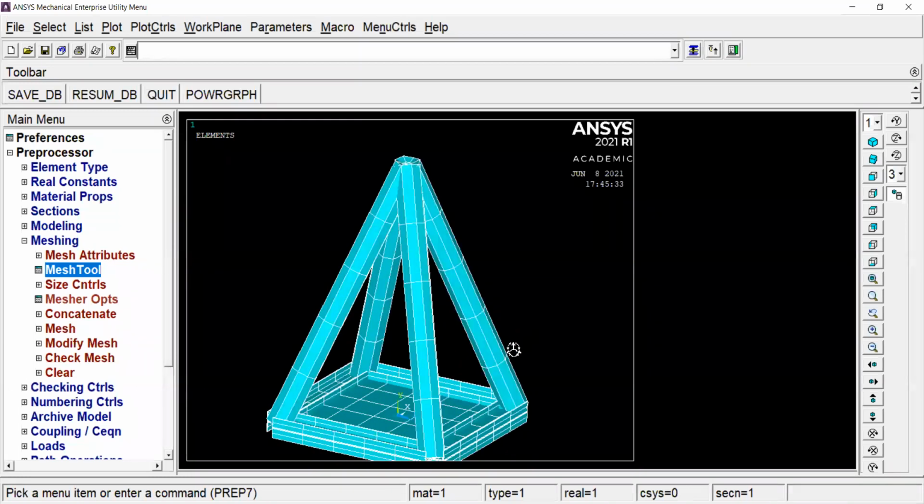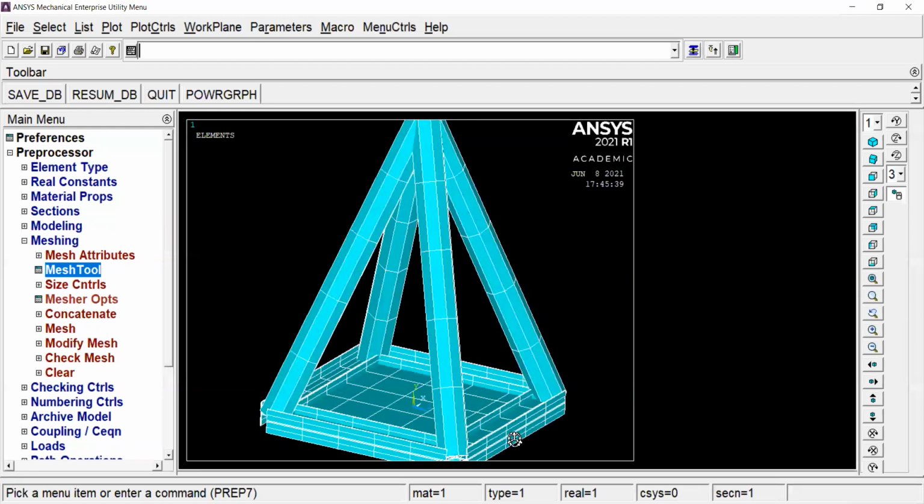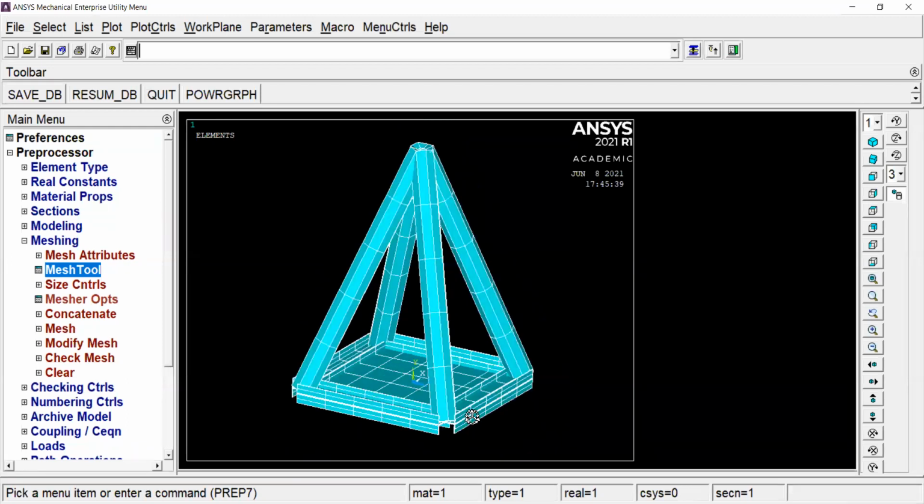But you'll notice that by default, the I-beams are set as H-beams, which means they're on their side. Now to orientate them properly, I will end this session now and start a new session with the same login information. And you can join that and I'll show you how to properly orient your I-beams so that the flanges are facing upright and not set on their side like this, so that the web is parallel to the y-axis. Okay, guys, so I'll just end the session now and start the next session where I'll demonstrate that bit.